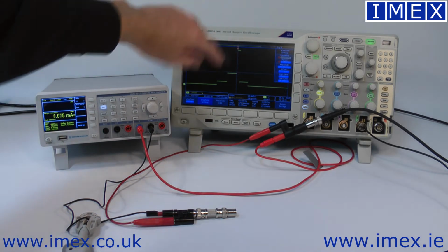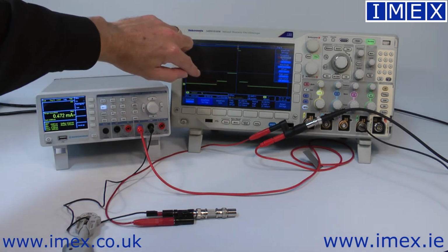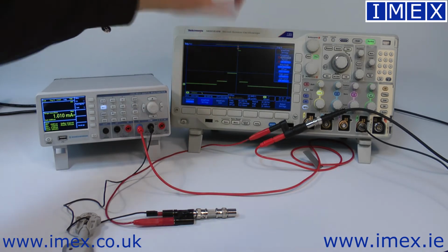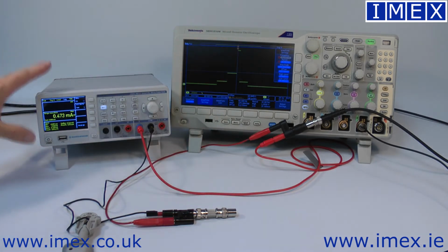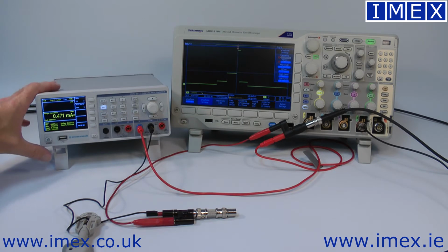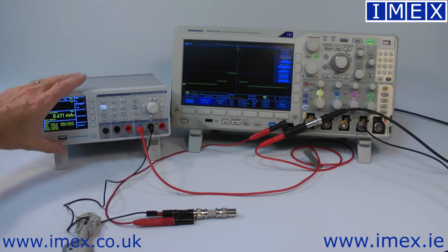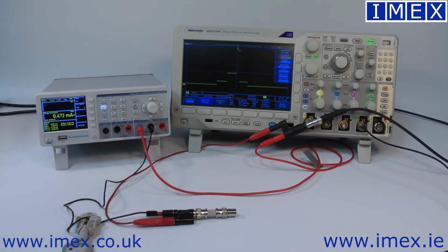You know, if you look at the scope, we're on 100 microseconds per division, that's roughly what, 30-40 microseconds I've set for that transmit duration. A normal DMM simply isn't fast enough to measure it. So we can rule this out as our instrument of choice. If we want to measure our current profile, we could use a current probe. So I also have one of those set up.